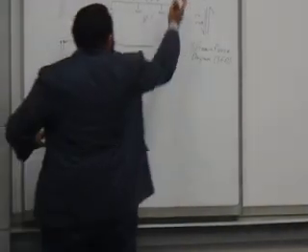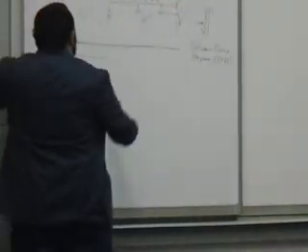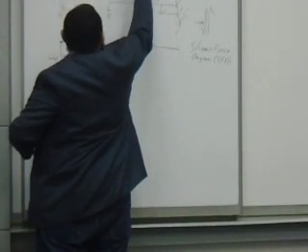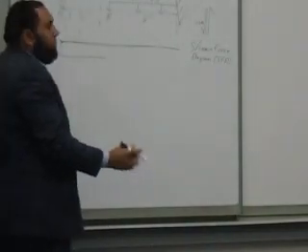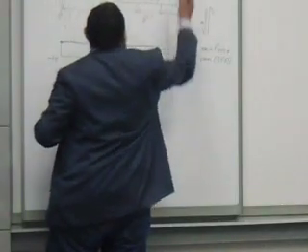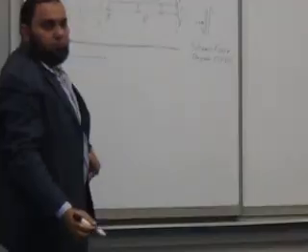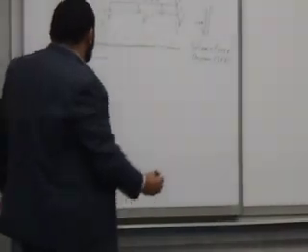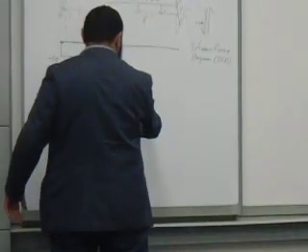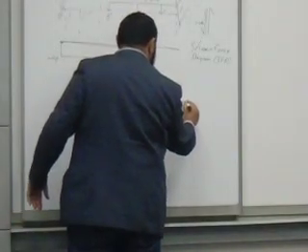But if I take a cut just before C, looking at everything, what I'm seeing is negative 4 minus 2 times 8. So this is equal to negative 20. Everything going down. So this is negative 4 and this is negative 20. I'm not drawing this to scale.